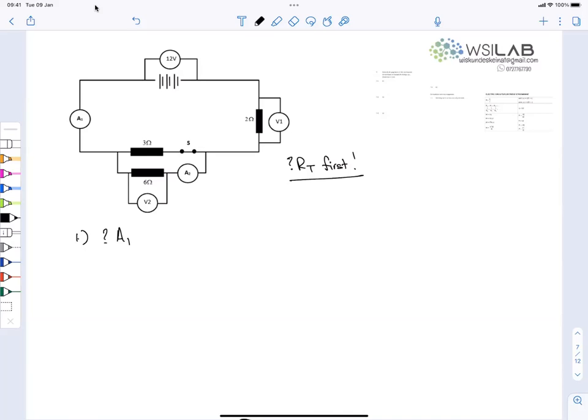Saskia, help me with the total resistance, please. It is the resistance in series plus the resistance in parallel. Is that correct? Yes, that's your equation. We have the series bit, which is 2 ohm. We don't have the parallel. 1 over R parallel is 1 over 3 plus 1 over 6, isn't it? Put that in your calculator and flip it around, and you'll get 2 ohm.